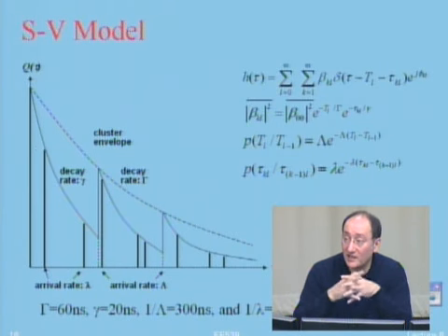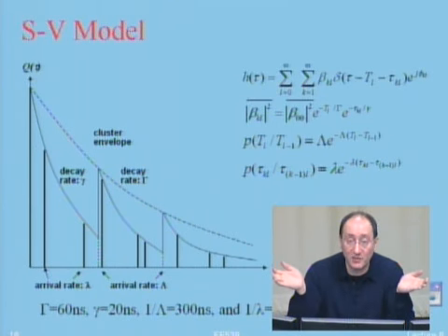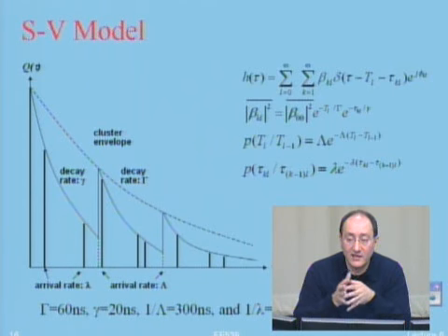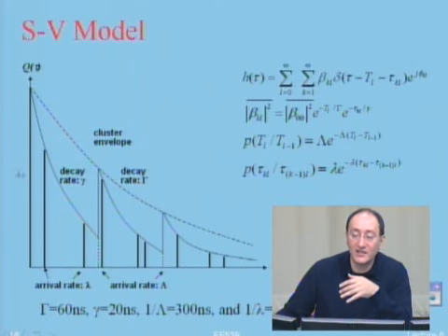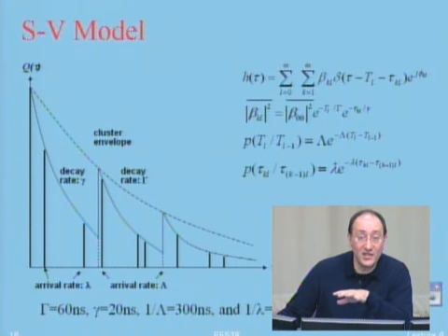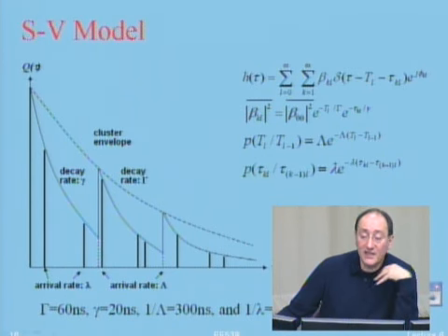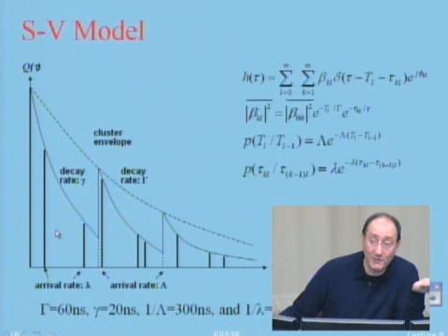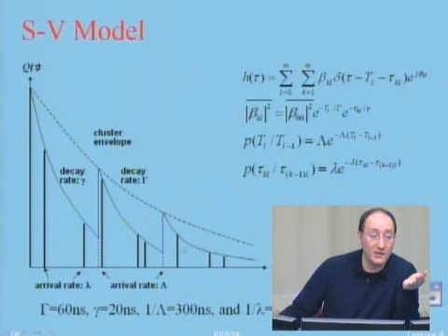If you remember, I told you earlier, when you do very wide band measurements, that's the time that the magnitude is not Rayleigh, is more like what? Log normal. Because you are averaging over variations of the channel with the bandwidth. And we need this type of model for that type of application, for wideband application. So there is a contradiction. 2 problems in this model. Problem 1 is that Poisson arrival is not correct. Number 2 is that Rayleigh assumption for this is not correct for wideband communication. And we need this for wideband communication.